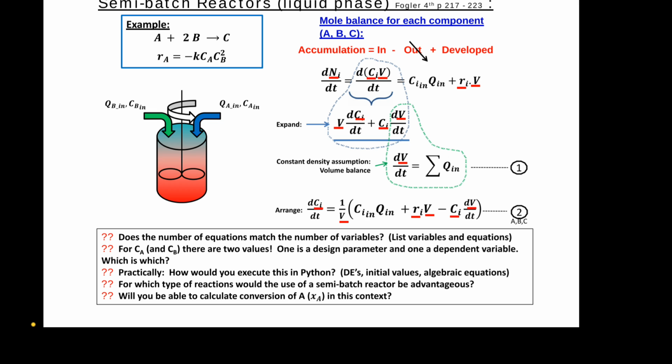The only risk with this approach is that you do not keep your ducks in a row and get confused with which concentration to use where. Remember, for Fn, you have to use the concentration at the inlet, which is not the same as the concentration inside that reactor.